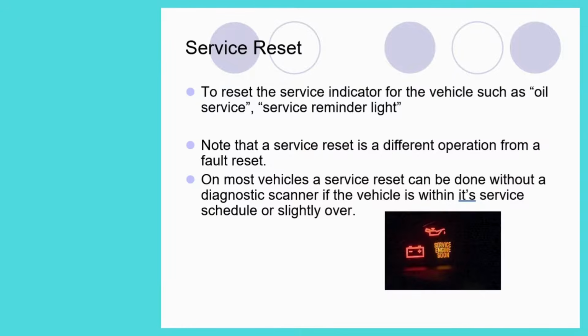To reset the service indicator for the vehicle, such as oil service or service reminder light. Note that a service reset is a different operation from a fault reset. On most vehicles, a service reset can be done without a diagnostic scanner if the vehicle is within its service schedule or slightly over, by a procedure on the dashboard.